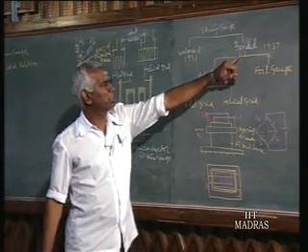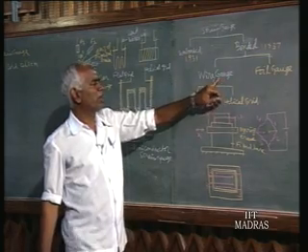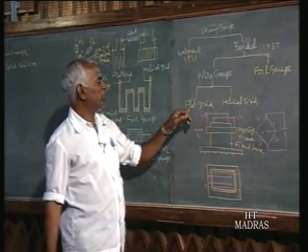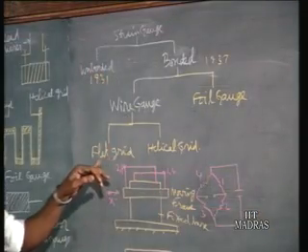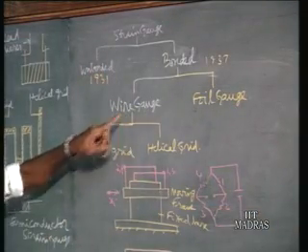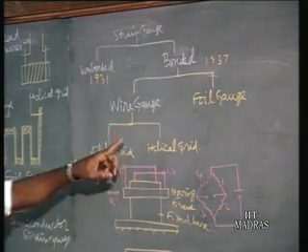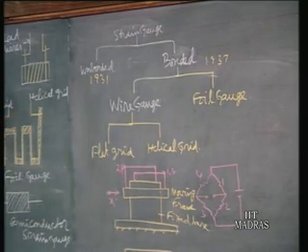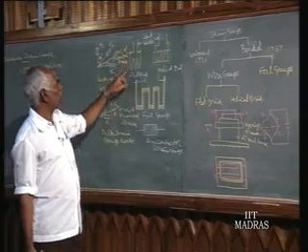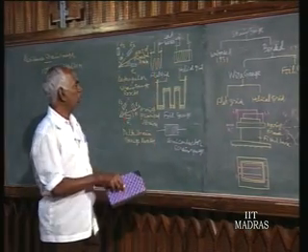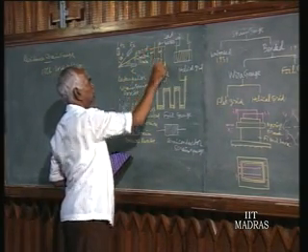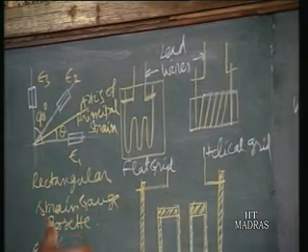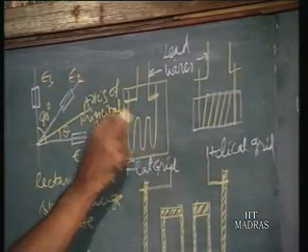And the bonded strain gauge, which came later, again has two types: wire gauge and foil gauge. In the wire gauge itself you have flat grid and helical grid. Flat is made up of wire, here it is foil. The wire is taken in zigzag fashion, and the whole thing is fixed in paper or plastic backing, two such packings, with cement to hold it in between.